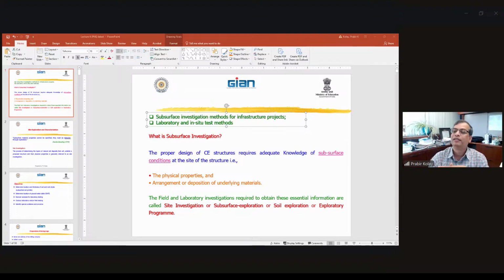Okay. Again, for a geotechnical engineer, it depends on the availability of the equipment. I'm in Southern Illinois, and even the Illinois Department of Transportation, although we know that CPT is better depending on the site, and it's more sophisticated and will give you the result immediately, people still use the SPT method.